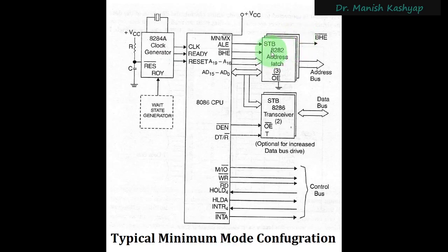And the name of this IC is Intel 8282 address latch. So this will be latching your addresses, right? And this address latch is always enabled, so we have made its OE bar pin, which is an enable pin, grounded. So what inputs does this address latch take? You can see that it takes the address latch enable signal first. This latch will be latching the addresses seeing the status of the ALE pin. If this ALE pin is high, it will use the address bus that you see here to latch its value into itself. So this ALE pin is required here.